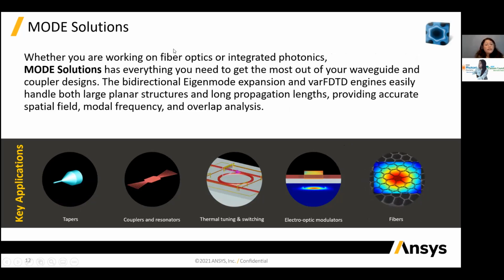So the mode solver, I'd like to say, is our waveguide design environment that can be used to do waveguide design, as well as different fiber design. The key applications for mode solver are tapers, which are longer devices that might take a long time to simulate if you want to solve the 3D Maxwell equation. But with mode solver, if you just want to see the cross section of the mode, that will be faster for the longer devices and so on.